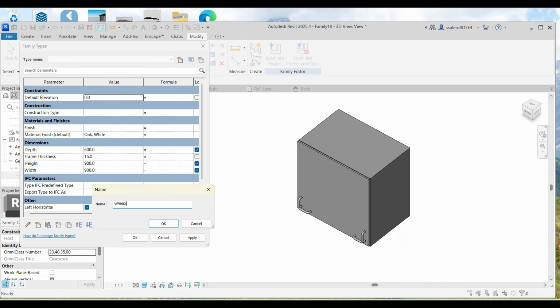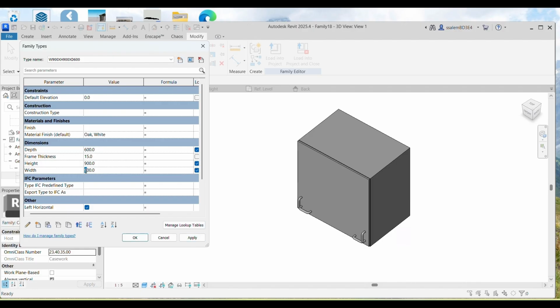And so that's done, and now I'm going to create a couple of default cabinets. I'm defining 3 standard widths: 300, 600, and 900 millimeters. And depth will always be the same. That's generally how it works with these cabinets, and height will keep at the moment at 900.